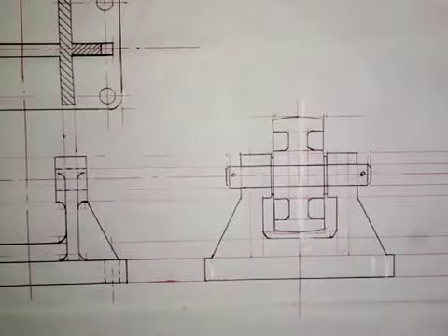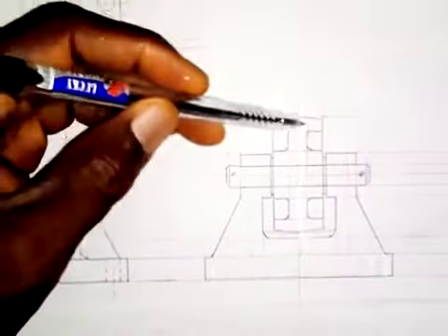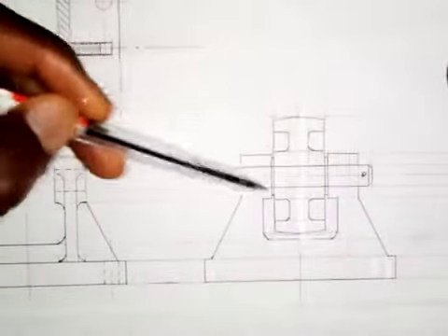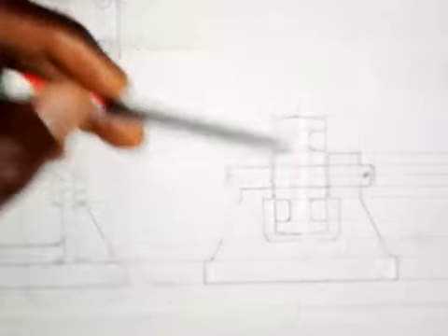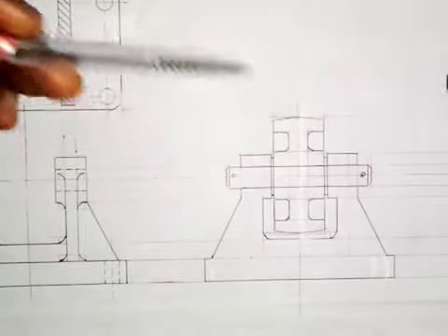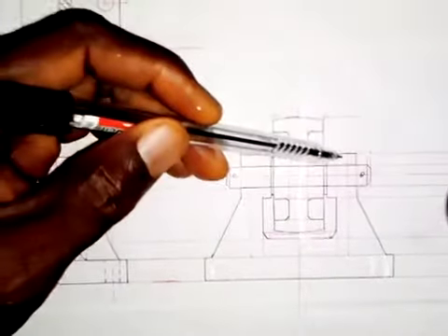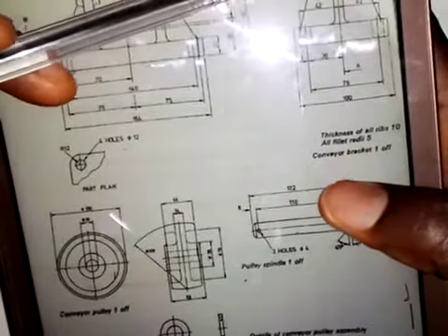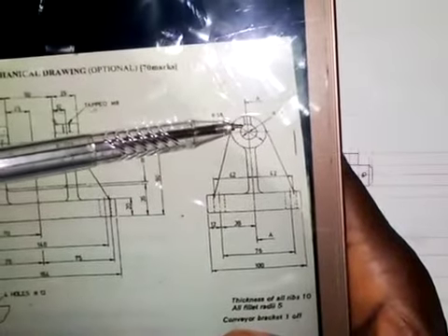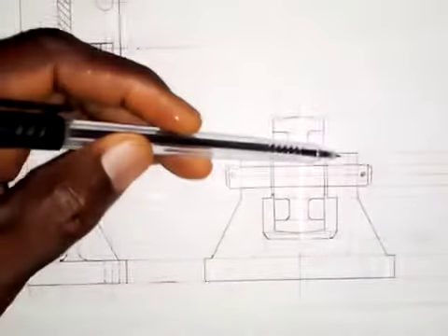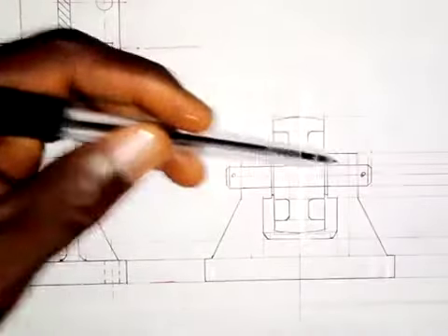All right, so this is what I've done so far. Nothing is hidden. This is the pulley, and if you have the question with you, you will see all that we are going to see inside, because by the time we assemble and put the pulley here with the spindle, we are going to cut part of this pulley, and we also cut the washer. So we are going to add some parts here. Those parts I'm going to add. And there is something here which I didn't put in the sectional, and in the given front elevation, we have a small hole here. This is where it is shown in the elevation. So we are supposed to have it here, and here, but I'm going to put it here.